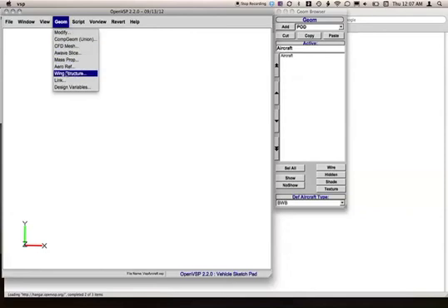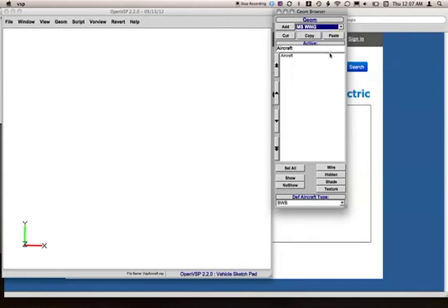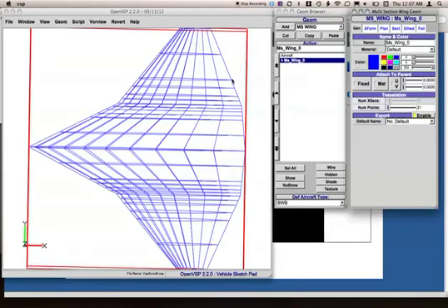Most of these, again, we won't talk about till later in the semester when we use some of the more advanced components of VSP. Now, to add a specific geometry, all you need to do is come in and say, okay, I'm going to add, for example, a wing, add, and there it is. And there's your default wing section.